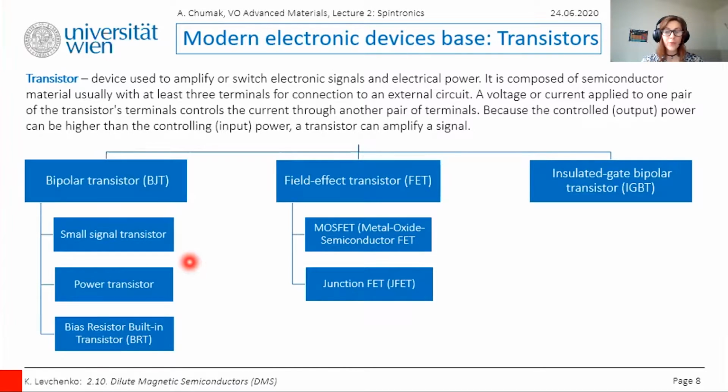The base is responsible for controlling the on and off switching states of the transistor, depending on the voltage applied to it. This type of transistor is mostly used in circuits because the majority carriers are electrons, and they have higher mobility than holes. But PNP transistors are still used.